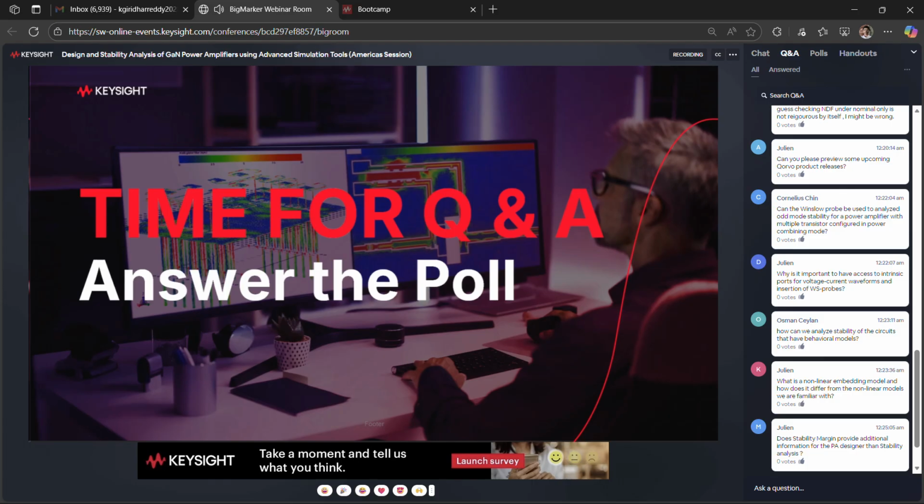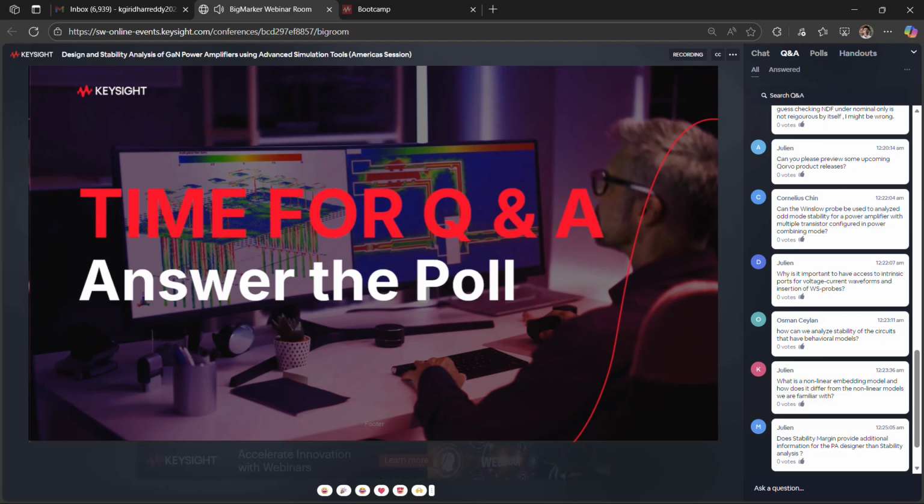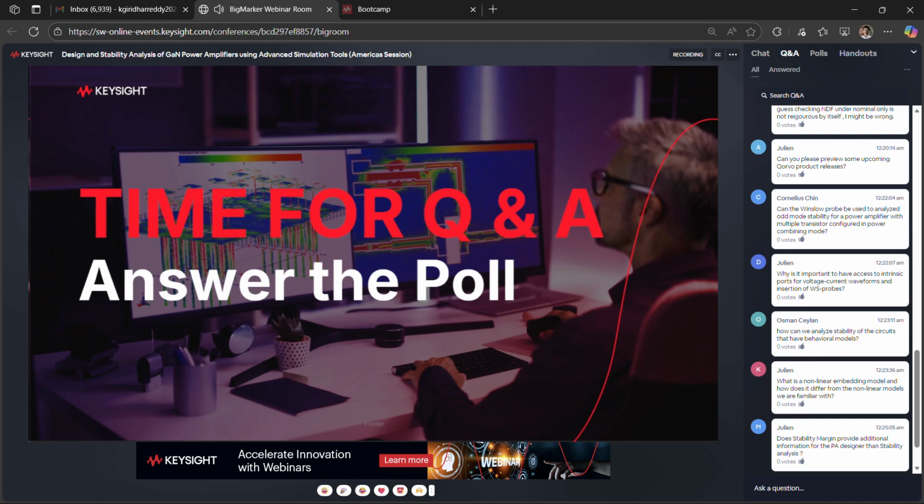Thanks for the question. The answer is yes, it provides additional information. If you think about the stability measures that I talked about today, normalized determinant function and driving point impedance or admittance, those are binary functions. So let's break it down. For the normalized determinant function, we measure stability through encirclements of the origin. The function itself either encircles the origin or it does not. There's no partial encirclement for that function. A partial encirclement says nothing. So we either say yes or no, that it's stable or unstable.